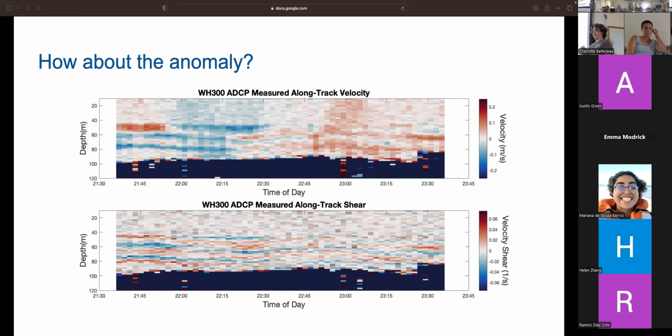And why can you see the surface? Because of the noise of the ship or something like that? Yeah, and so for the ships especially, when you emit your sound, it's going to bounce off the hull, because a lot of times they're in recessed cavities in the hull itself. Remember the beam pattern I drew, with the little side bits? Those go off sideways and then come back into the beam. So you're not actually hearing the stuff in front, you're just hearing the returns from the side. That's why we have to cut off a little bit extra, because it contaminates.